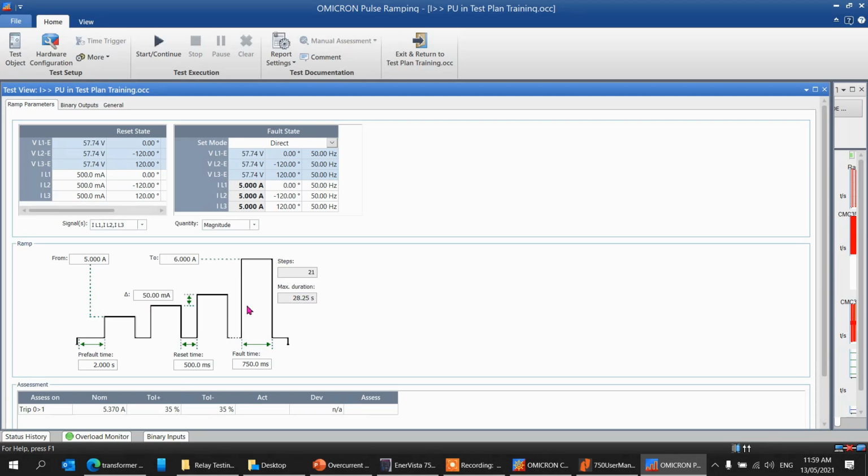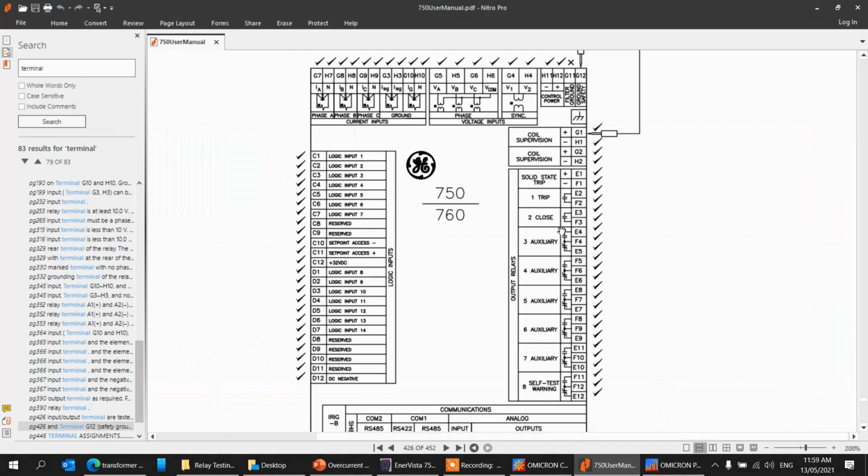Instantaneous will trip instantly, of course. But when you're doing it on the IDMT, how do you do it in this sort of setup? There's a difference in the relay. In the relay, you can also assign some pickup signal. Some other relays are capable of assigning the pickup. So you put that signal on that specific protection.